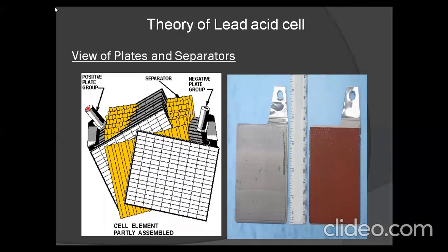The Planté plates have low capacity weight ratio. The Faure or pasted plates are much more suitable for manufacturing of negative plates rather than positive plates. The negative active material is quite tough and it undergoes a comparatively low change from charging and discharging.